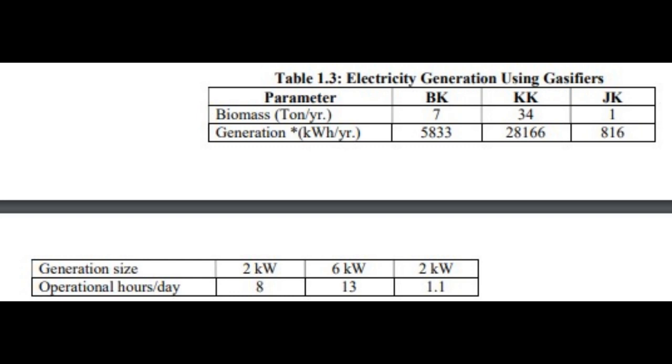Look at the screen. Note the fuel, biomass and diesel, consumption rate per kilowatt of power production: 1 to 1.2 kilograms of biomass and 0.8 to 1 liter of diesel. It may be mentioned that the cost data for gasifier generation systems in Indian conditions are inadequately available. The cost data are available for the Jyoti gasifier. The range of power production varies from 2 kilowatts, model G15, to 40 to 120 kilowatts for model G300. The capital cost for power production is about Rs. 1,200 per kilowatt.